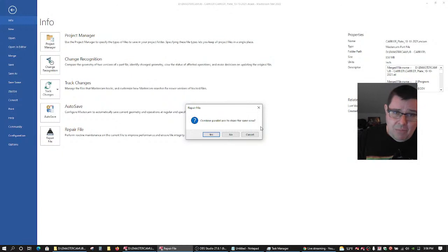So if it's on a drilling path, we're going to lose the arcs that were assigned to that drill toolpath. And if it is part of a chain, we're going to lose the chain. And the worst is that sometimes you can just end up with a partial chain. So you'll regenerate the path. The path will look good because, hey, it's running where we told it to run. But the reality is it's chopped out part of the rest of our chain, and now we're going to have to go back and fix that stuff.